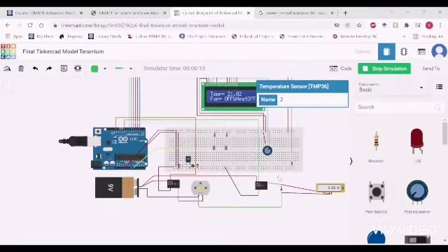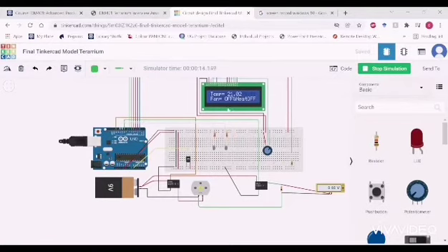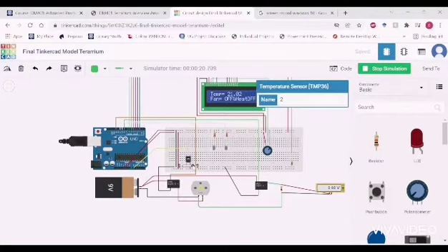So this here is the simulation within Tinkercad, and this is the virtual simulation. So the temperature here is set to 21 degrees, which is within the range of 21 to 25 degrees, so the plant is growing effectively, and therefore both the heater and the fan are turned off. If I was to turn the temperature to a lower temperature, below 21 degrees, then the heating element turns on, which is represented by the resistor here, and can be seen with the LED turned on, as well as the reading from the voltmeter is high.